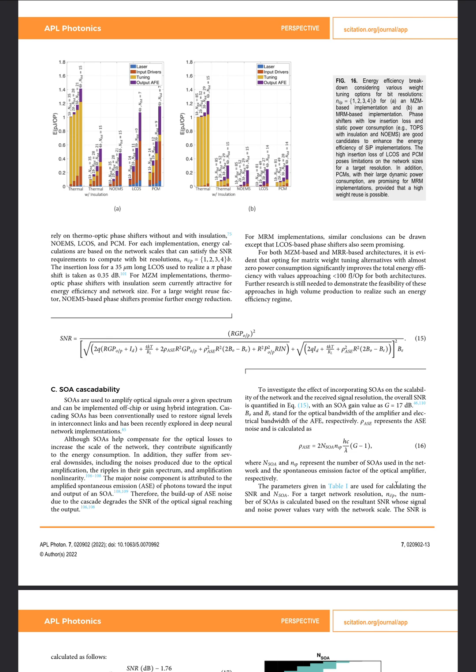The signal-to-noise ratio is borderline unusable in non-semiconductor optical amplifierless networks, and semiconductor optical amplifiers can be added in the network before the signal-to-noise ratio degrades below the threshold. Signal-dependent noises, however, get amplified.